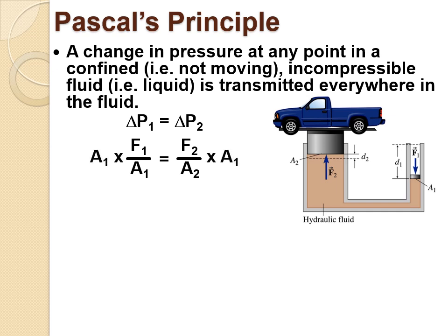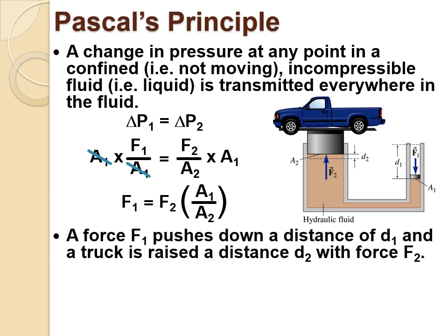So if we rearrange this equation, we can see that the force being applied on this side is going to be equal to the force on the other side times the ratio of the areas where the forces are being applied. Now, just to show why this principle works, I'm going to take this equation and show you that the work being done, force times displacement, is the same on this side as it is over here.